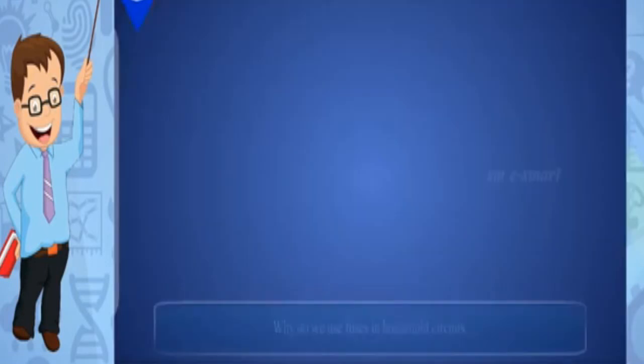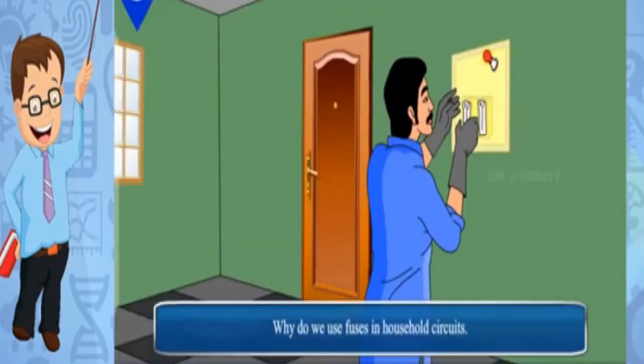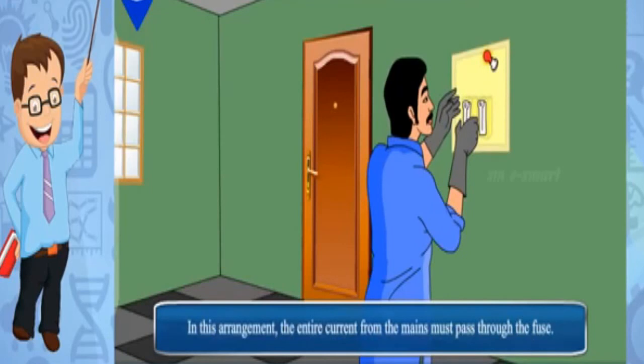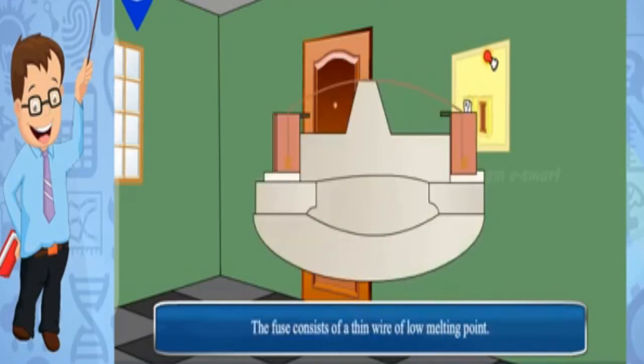Why do we use fuses in household circuits? To prevent damage due to overloading, we connect an electric fuse to the household circuit. In this arrangement, the entire current from the mains must pass through the fuse. The fuse consists of a thin wire of low melting point.